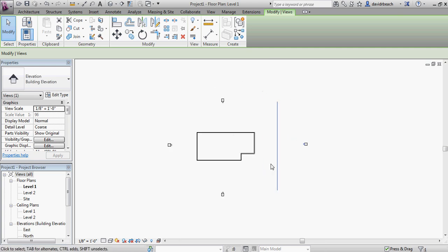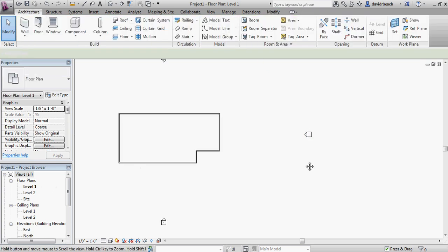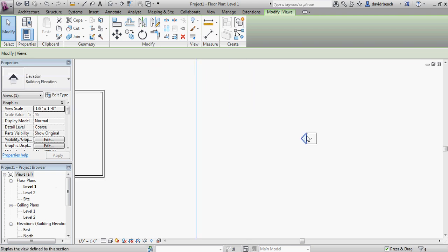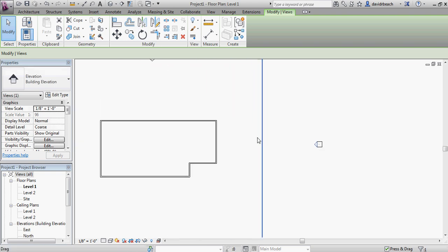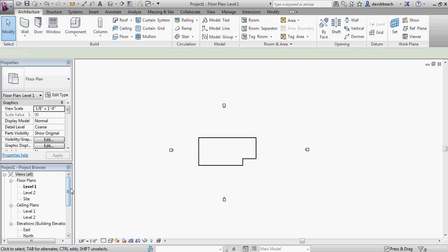So remember, in Revit, everything's 3D. So essentially, every two-dimensional view is a sectional view someplace. Right now, again, my bold is level 1, so I'm in a floor plan view, which is a section cut, by default 4 feet above the finished floor elevation of level 1, looking down. So an elevation, again, is actually a section looking this direction, as denoted by this arrow, and that essentially is my section plane.